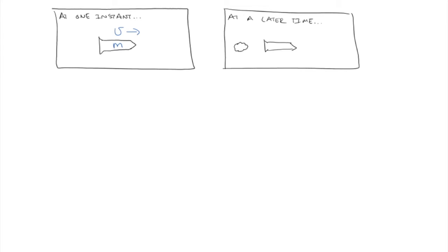The rocket now has the mass m minus dm and is moving slightly faster, so we'll call it v plus dv. The gas has the mass of dm and is moving with velocity v plus dv, which is what the rocket was, plus u, where u is the relative speed at which the exhaust is ejected from the rocket. In this case, u would be a negative number because the rocket is shooting the exhaust out the back to the left in the drawing relative to the rocket.